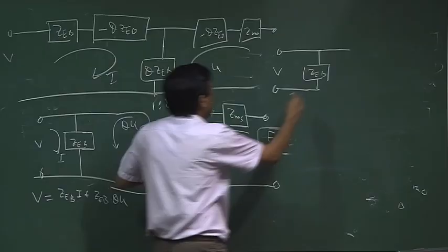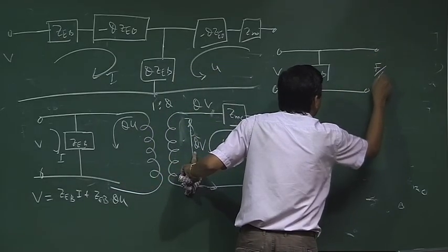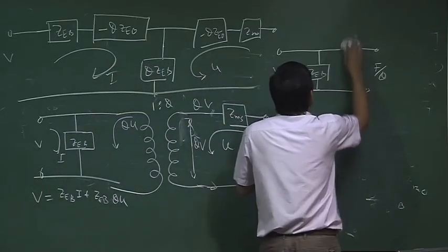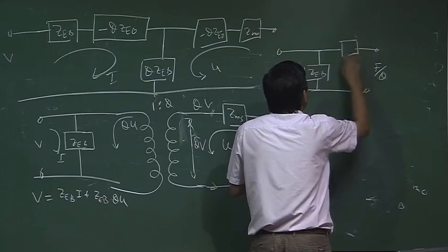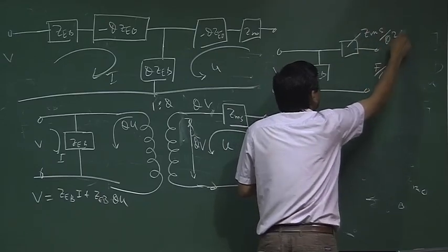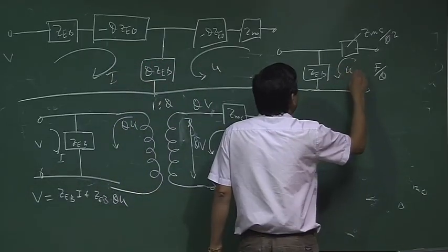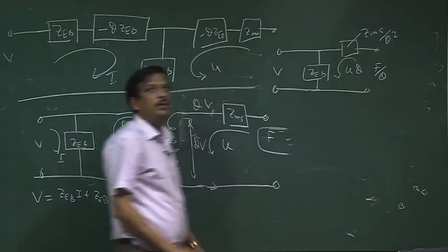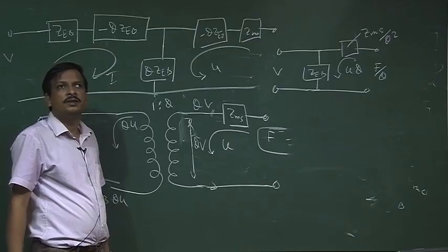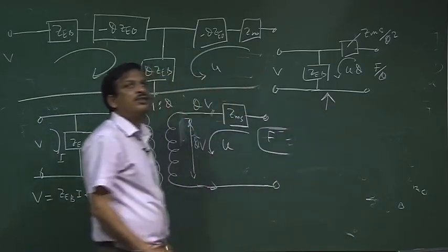So, let us say the mechanical force is reduced by phi. Okay. So, this impedance will be ZMS by phi square, and the current will be U into phi. So, that can be an equivalent circuit. Okay. So, this is the equivalent circuit for a reciprocal transducer.